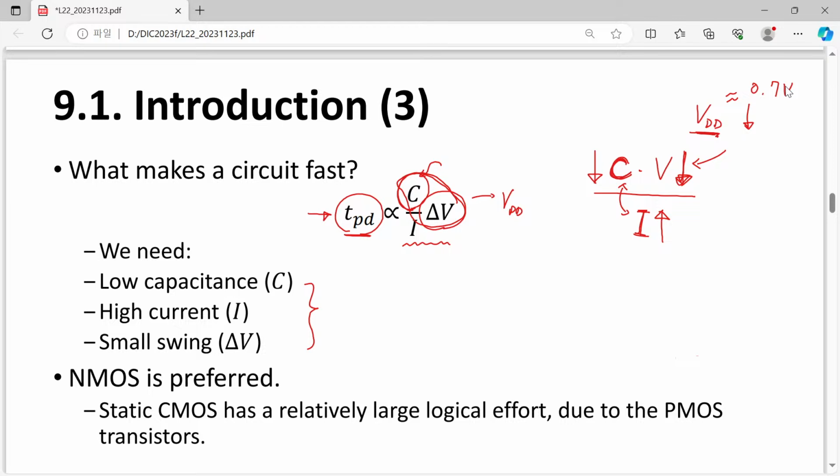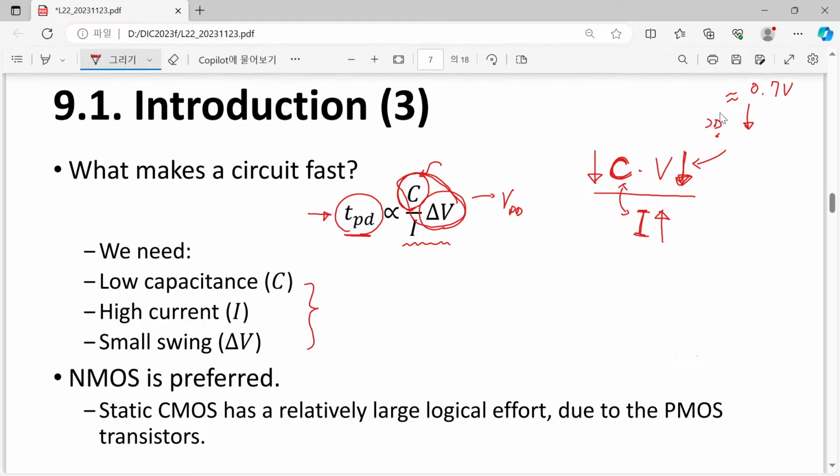That is still 0.7. Sometimes we can find some literature with 0.65, but we have no significant further reduction of VDD, because our transistor requires a certain separation between its off value and on value, as it has a limited maximum subthreshold slope. Everybody can understand this one.